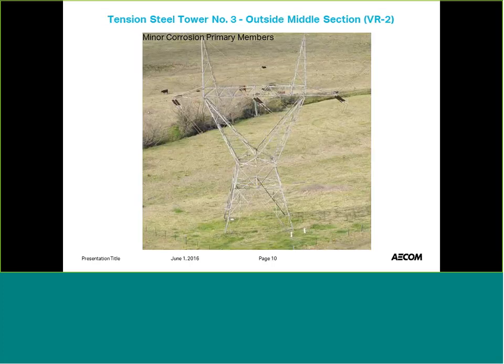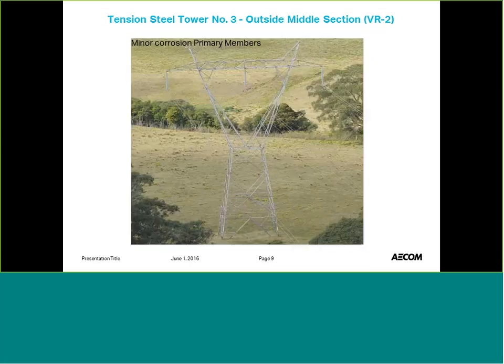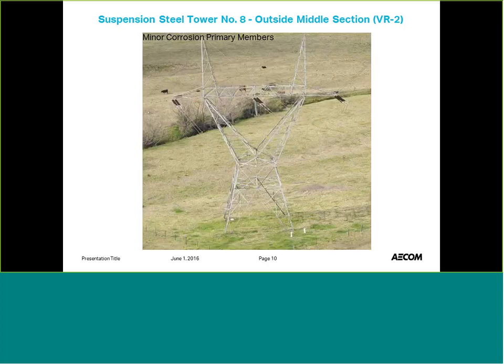This now is a middle section tower. I'll just go back to that one. As you can see, the visual rating on that tower is a VR2. That tower is over 55 years old, and it's in a relatively good, sound condition.